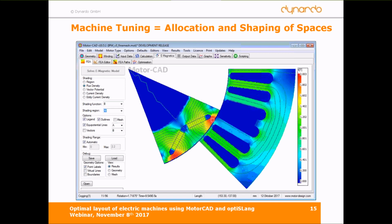Just like that, you have to find compromises between having iron here for conducting the magnetic field lines, or having copper here for having the largest possible cross-section to get the current through without ohmic losses. So that's the next trade-off.